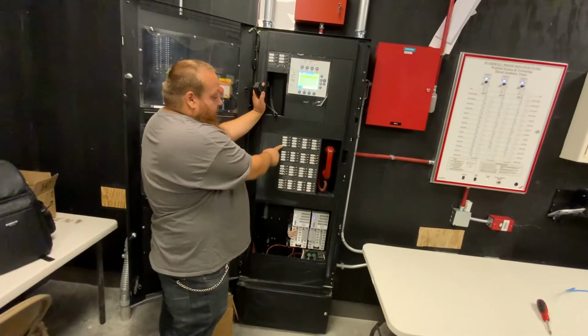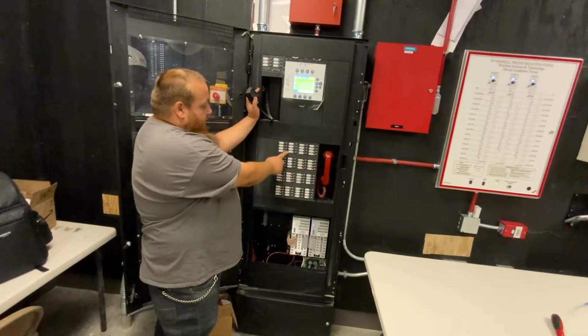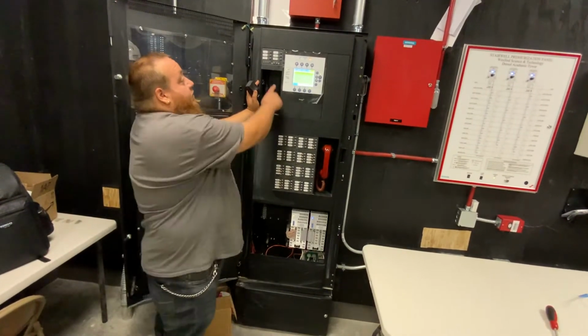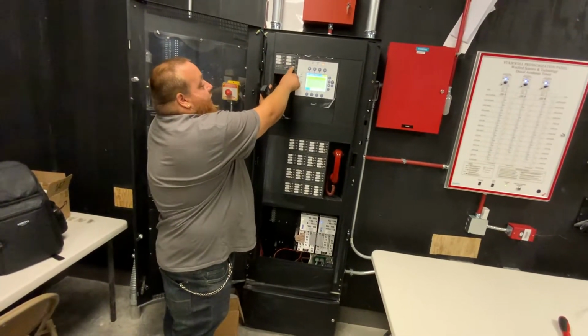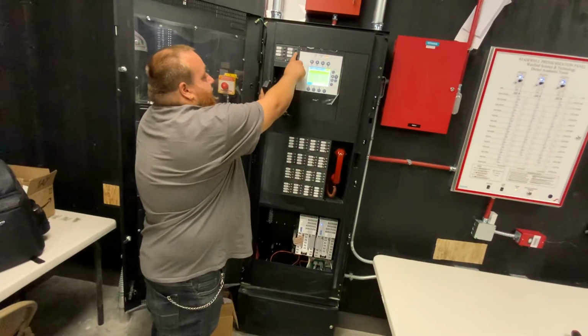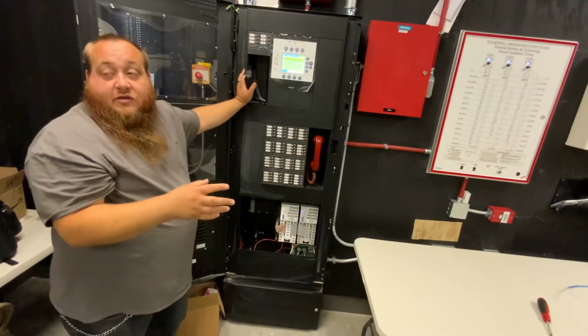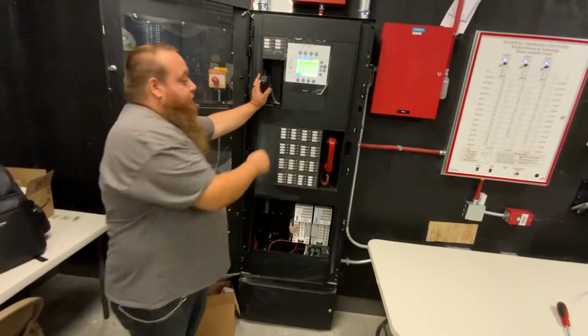See how it's still blinking? You still have that floor enabled. Simply select it, and it'll turn off. That same applies for a select evac and select alert. You would hit these buttons, and any floor I would hit, that evacuation message would go just to that floor.